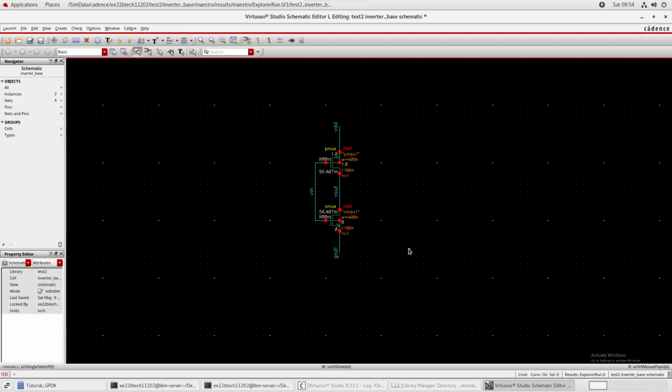I've seen this happen a lot of times where people include these things in their designs and then shift delete them. Shift delete as in ignore. You select any device and press shift delete, it just ignores it. So in your simulation this won't appear, it will be ignored. Never do this. If you have a design, just keep it a simple design which you can realize on silicon.